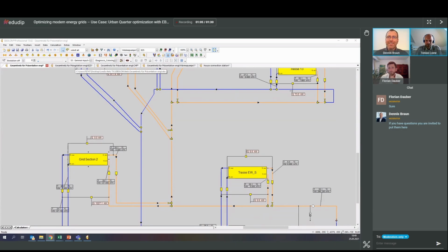Yeah, the computer hardware. So Epsilon usually runs on your desktop PC. Of course, you can run it on a multi-core server, and they benefit from the multi-cores. But a model like Florian's can definitely run on a laptop. You may be a bit slower, but only in the percentage area compared to a server, because the calculation of a single model usually runs faster when it's run sequentially. We have multi-core support, but that usually only benefits when you have really hard fluids.